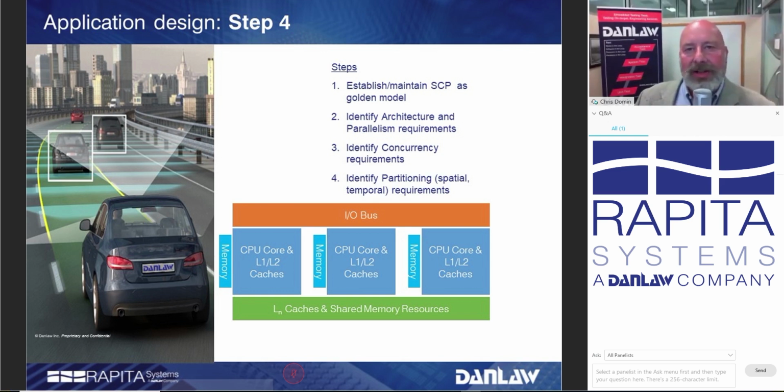So what I'm trying to say is that the trade-offs between partitioning decisions, real-time performance needs, and worst-case execution times should be balanced with each other. And experienced software designers usually do a pretty good job of that, and they make common sense decisions on how to do that. But there's still some challenges, and it really comes to when you talk about functional safety.